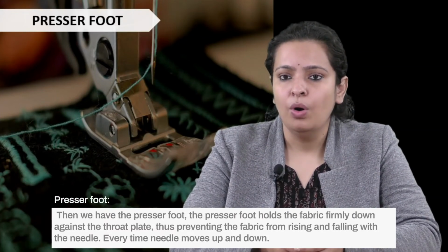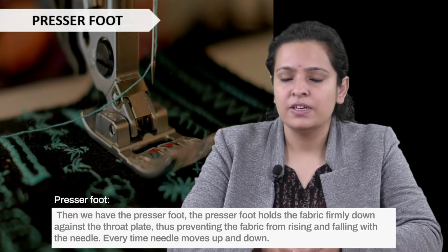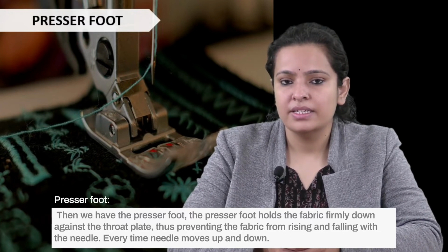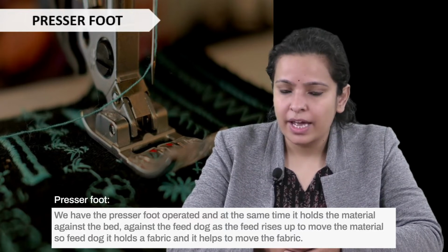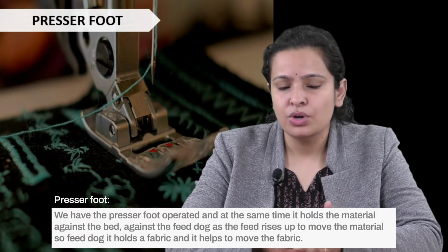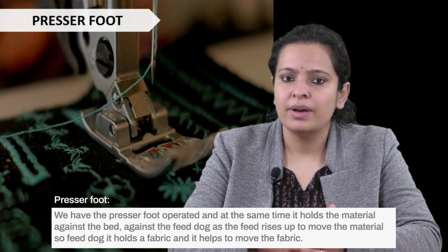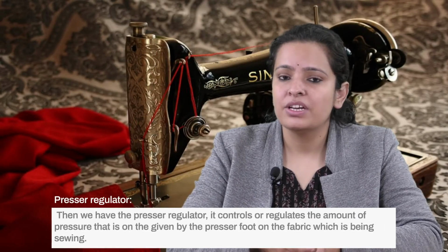The pressure foot holds the fabric firmly down against the throat plate, thus preventing the fabric from rising and falling with the needle. Every time the needle moves up and down, we have the pressure foot operating. At the same time, it holds the material against the bed, against the feed dog, as the feed rises up to move the material. So the feed dog holds the fabric and helps to move it. Then we have the pressure regulator.